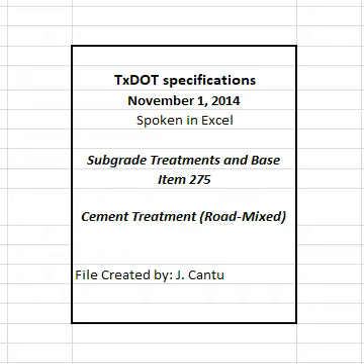4. Construction. Construct each layer uniformly, free of loose or segregated areas and with the required density and moisture content. Provide a smooth surface that conforms to the typical sections, lines, and grades shown on the plans or as directed. 4.1 Preparation of subgrade or existing base for treatment. Before treating, remove existing asphalt concrete pavement in accordance with pertinent items and the plans or as directed.